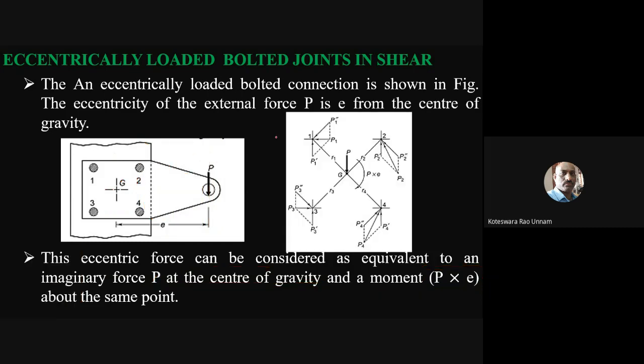So for that, okay, this is the free body diagram of these bolts. So what you can see here is our center of gravity where the force is applied, whose magnitude is P, and a moment of P into E is applied here.